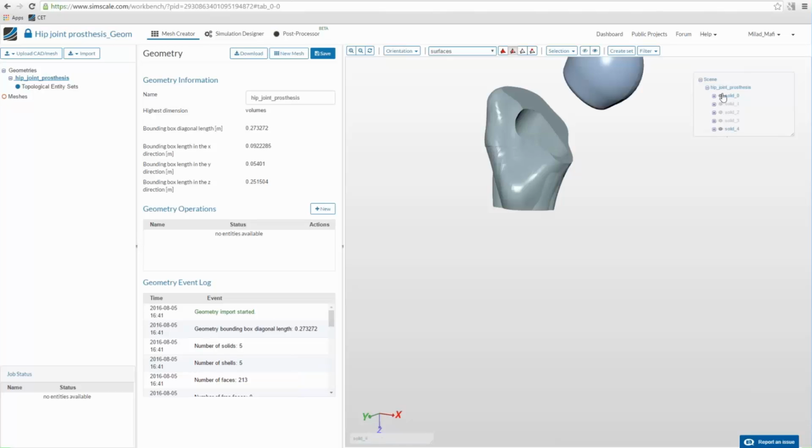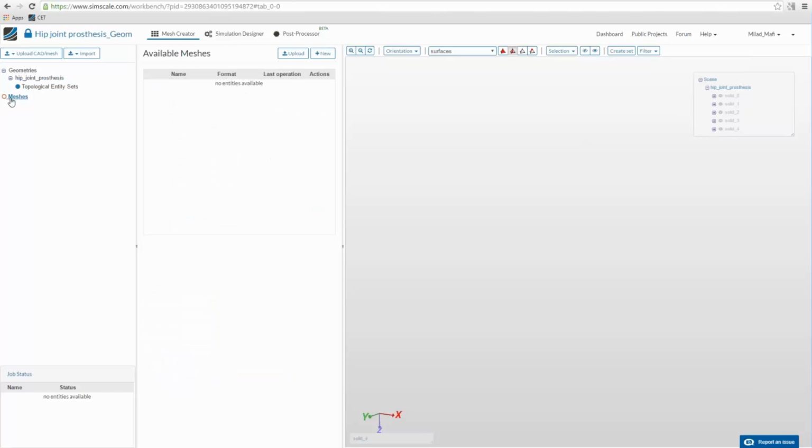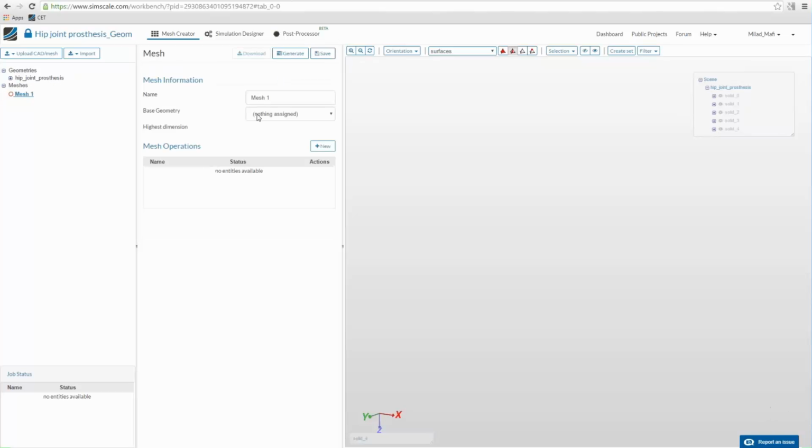We have the bone marrow, which is blue, and we have the gray trabecular bone. And right now we will divide this geometry into small cells to have a computational mesh to perform the simulation. Because you should not forget, later on, the simulation tool is only calculating quantities like stress, forces, and displacement for these cells.